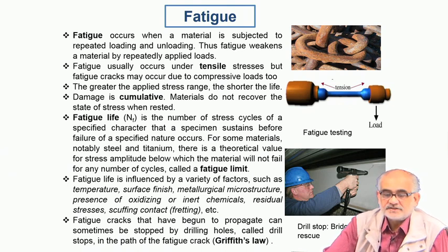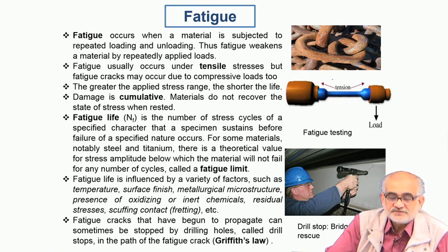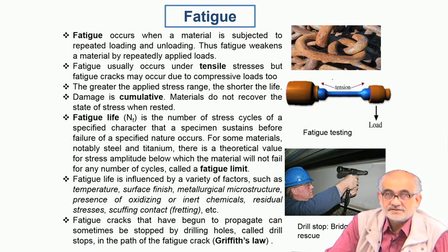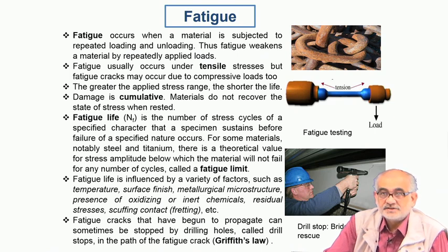So whenever we encounter such a cyclic loading condition, what one needs to be very careful about is to figure out whether we have a discontinuity already existing, for example a crack or a dent or some kind of scratch with a sharp tip existing on the surface, and whether the surface is experiencing tensile loading.